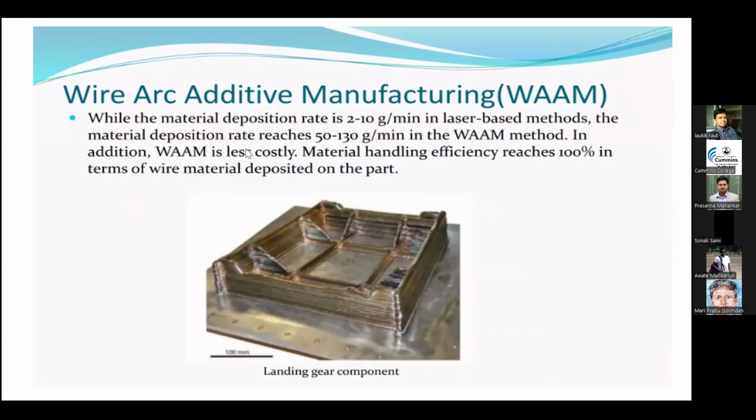Then, WAAM is less costly, as we are using existing welding techniques. GTAW, GMAW, these machines are very economical, and we are using those machines to deposit the material. So WAAM is less costly as compared to laser-based 3D printers.